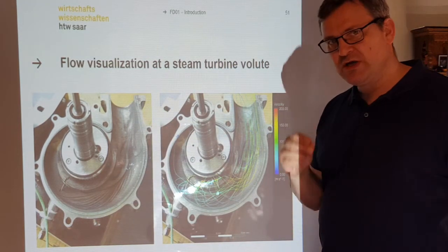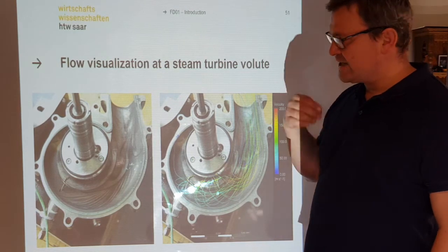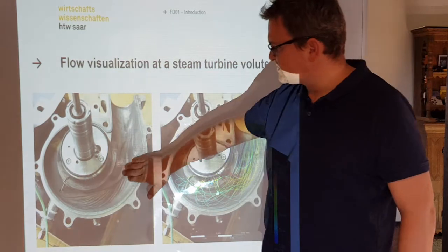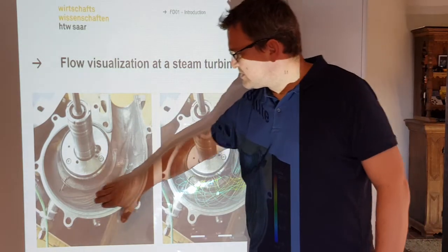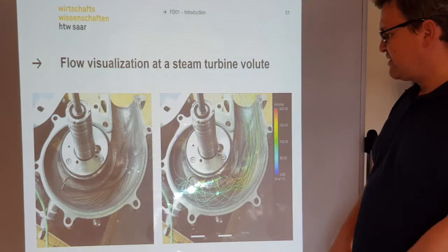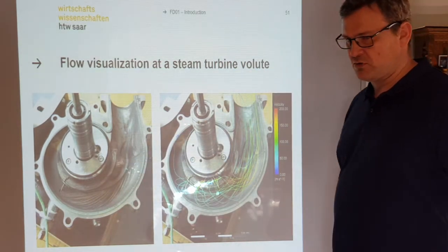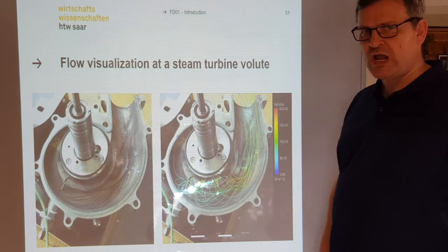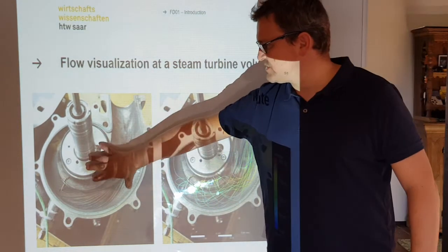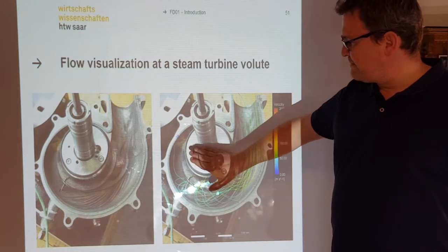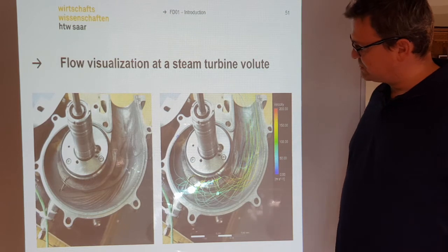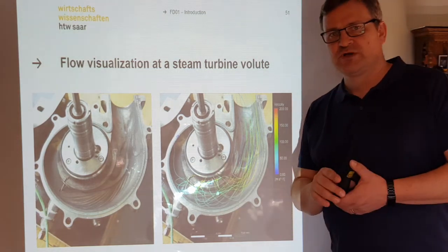We put some oil into the turbine, we got some soot and smoke particles, and they built a streamline at the housing of the turbine, so we could get an estimation about the fluid flow. And I also made a computational fluid dynamics simulation of this geometry, and I placed the CFD result over the turbine geometry, and it fitted really well.